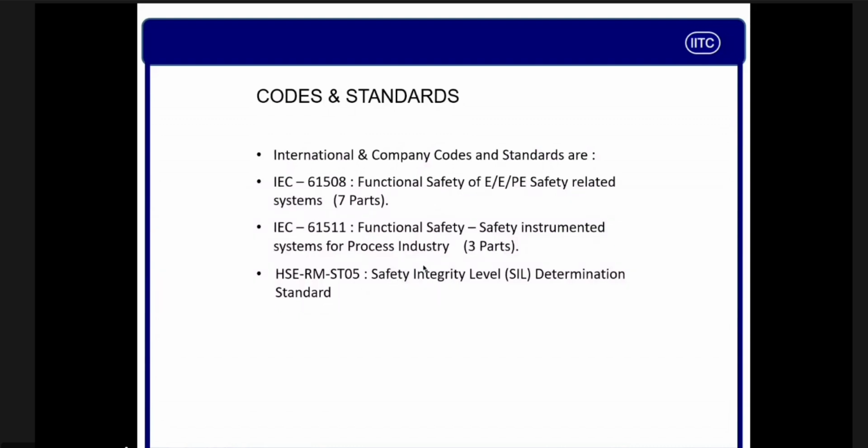And of course, ADNOC has a beautiful standard and system, HSE RM ST05, which dedicatedly informs the methodology and approach: how we need to identify the SIF, how we need to evaluate the TMEL, how we need to evaluate the consequences, how we need to identify the conditional modifiers, and we will take all the initiating events, identify the initiating event likelihood, and of course identify all the IPLs, and then give the PFD of the IPLs.